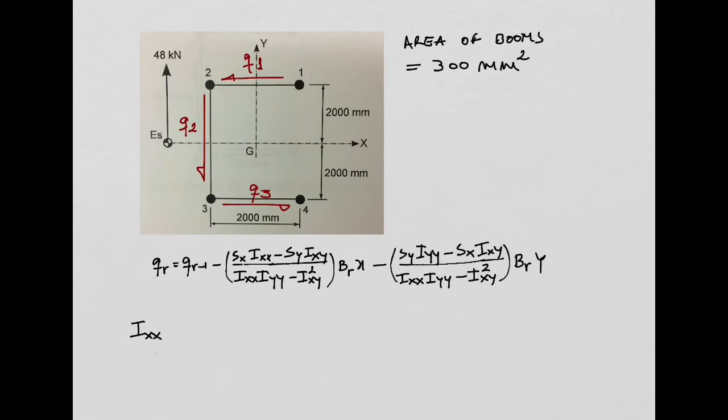If I have an idealized structure like this with booms, don't forget, we are assuming the skins have 0 thickness, right? So everything is concentrated on the booms. So how do I calculate, in an idealized cross-section, the second moment of area about the x-axis?